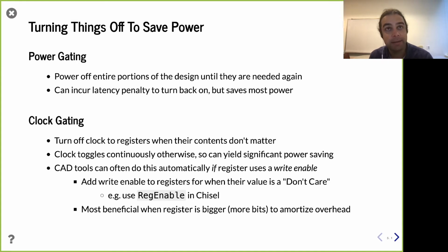The clock gating is a different one. It's a little bit interesting, right? So the clock gating is recognizing, going back to activity factor, that if things aren't changing, we can save power. If things aren't changing, we can reduce our activity factor, and reducing activity factor saves power. And so what clock gating is recognizing is that this is a portion of the design where it also is not currently being needed. That's why we're able to turn it off.